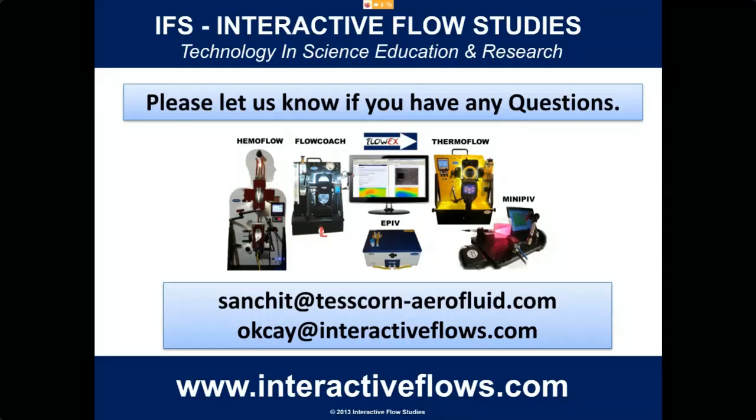Okay. So first of all, measuring using PIV near the boundary layers is really difficult because near the boundary layers you have high shear gradients, and to get particles into that layer is really, really hard. That's one problem. So your seed density is really low down there, close to the walls, and you need a good amount of seeding to get good PIV data. Secondly, reflection. So when you shine a laser or an LED onto a surface, it reflects. So right on the boundary, it's quite tricky.